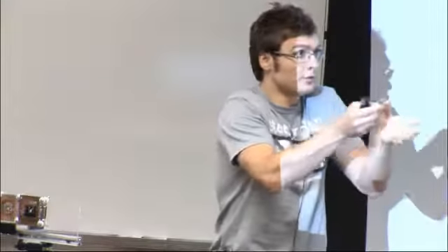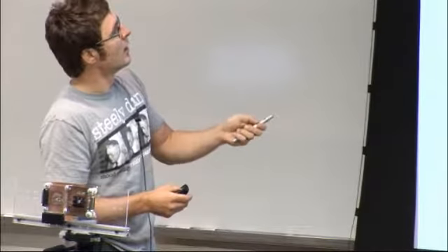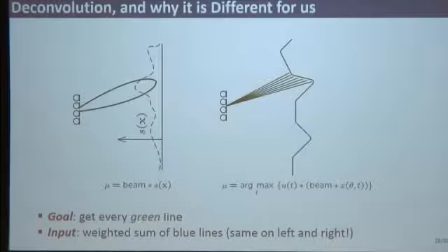And so imagine that the wall is created by very small pixels of noise, something smallest that you can detect. Then I direct my beamformer towards a certain part of that wall, and I'm not able to listen to individual pixels. What I'll be listening to when I direct the beamformer in some direction is a weighted sum of all these pixels. I was trying to represent this here, mildly successfully. So you get the weighted sum of this intensity across the beam shape, okay?